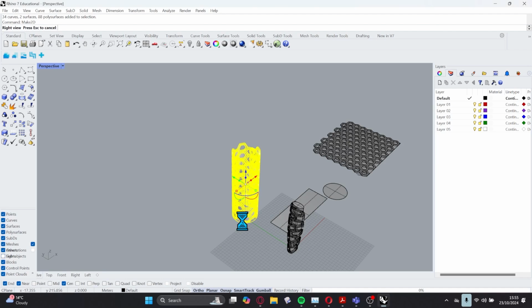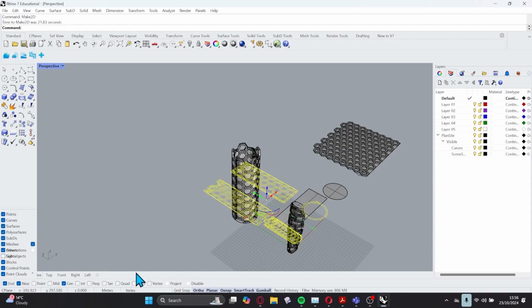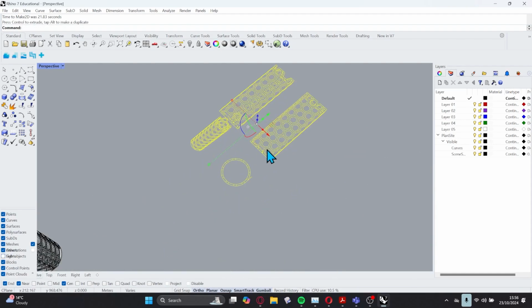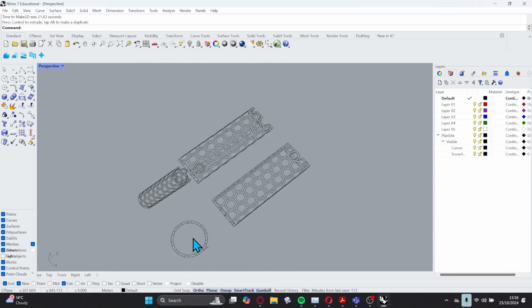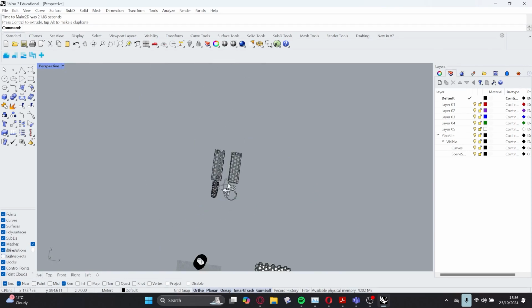what you'll see now starts to happen is that we'll be able to create 2D drawings from our 3D model. And it will create curves from the geometry. So it's going to take elevations, a plan, and also a 3D view. So you see here now. So let's say, for example, top, if I just go over here. So you see now what I've been able to create. I now have elevations of that and a 3D and a plan. So we've got 2 elevations, a 3D perspective view, and we have also a plan of that.